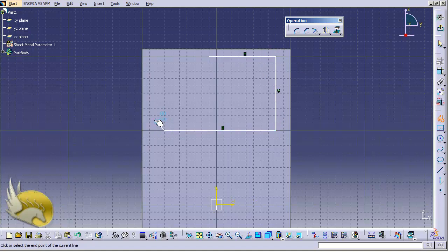I want to have a 45 degrees, or better to say 135 degree side here. Go up, go right, and again another 45 degrees here. I can remove this parallelism and perpendicularism here. I don't want to have this. I can add my own constraints, for example, the angle values. And of course, they wouldn't harm my shape.